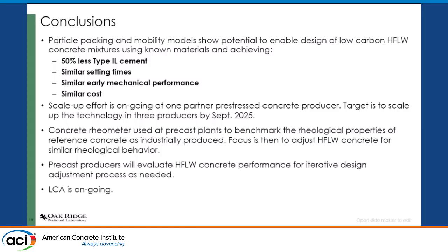We want to see what changes in raw material variability, process variability, and other variabilities will affect the performance of high filler. We do bring the concrete rheometer to the plant because we want to estimate what is the energy that the reference is taking out of their industrial mixer so we can try to match that. So again, we rely a lot on their experience to tell us if the concrete is good or bad, does it need to be refined, and so on. So LCA is ongoing, and with that, I'm available for questions. Thank you.